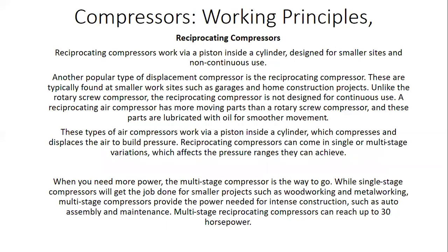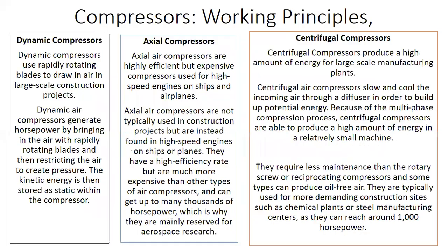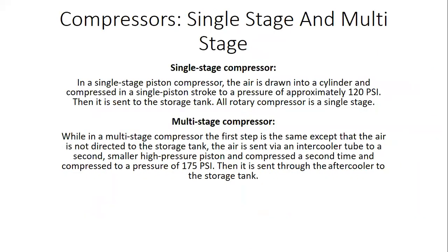creating more than one piston, so that you will not have a single stage compressor, you have a multiple stage compressor. So what is a single stage and a multiple stage compressor? The former one, the single stage, involves air being drawn into a cylinder and compressed by a single piston stroke to a pressure of approximately 120 psi. Then it is sent to the storage tank. All rotary compressors are single stage compressors.